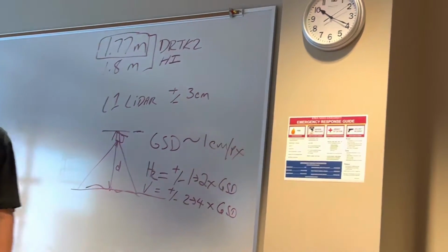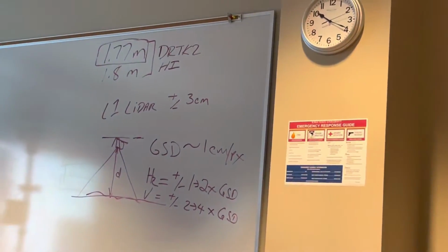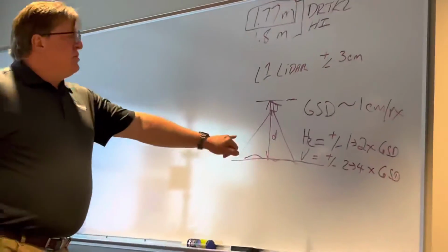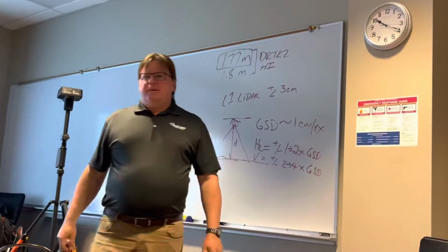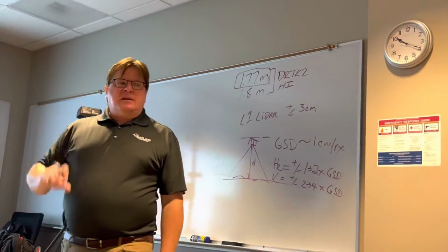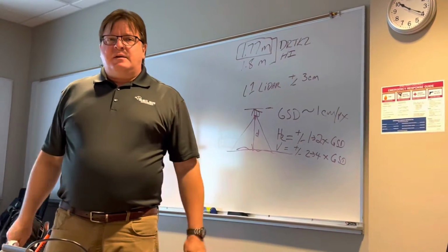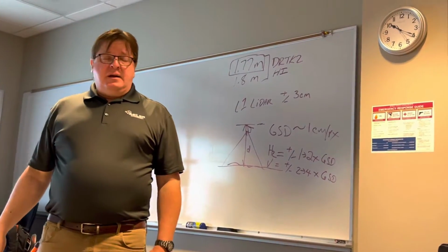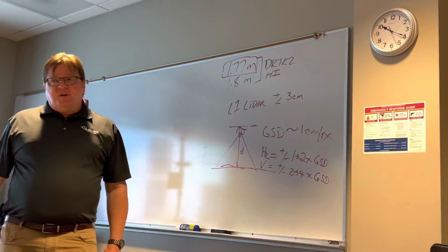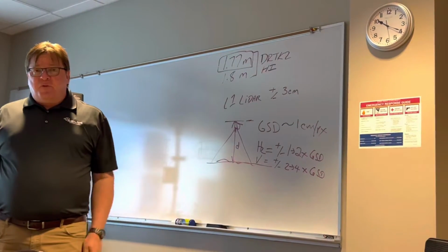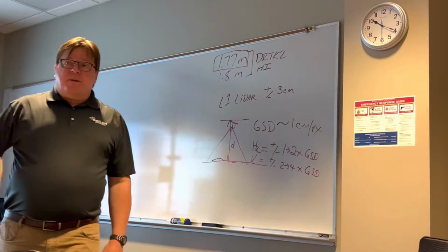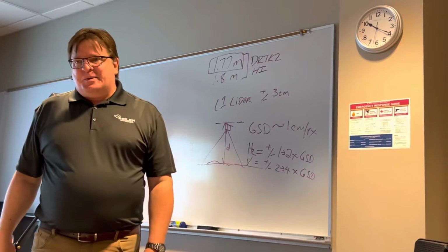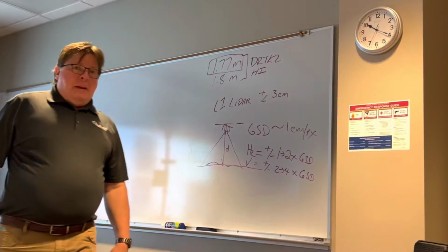So we can say when we do our models for photogrammetry, and my photogrammetry is calculated out by 1 centimeter per pixel, my final model is going to be plus or minus horizontally 2 centimeters. So I'll be within an inch horizontally. Vertically, 1 to 2 inches, which is not bad for photogrammetry. Old style photogrammetry was maybe plus or minus 6 inches to a foot vertically. It was horrible. All right.